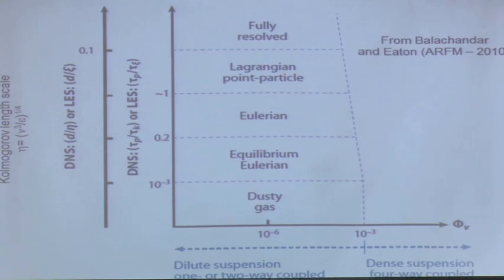And what I mean by small or big is not the size, is not 10 microns, 50 microns, 1 millimeter, 1 centimeter, it is the ratio of the size with the turbulent scales. This is what is important. The real size, we don't care. It's really, do we need to mesh the flow around the particles because we have flow structure at this scale, or we don't need. Okay?